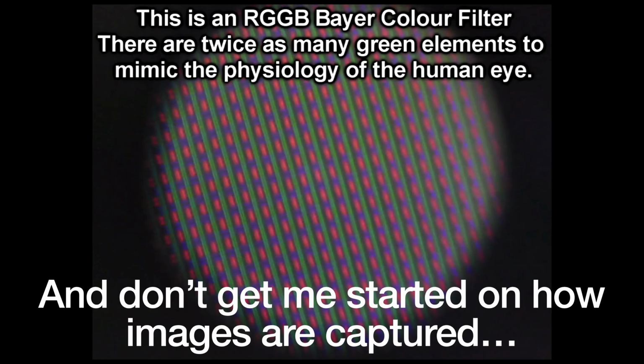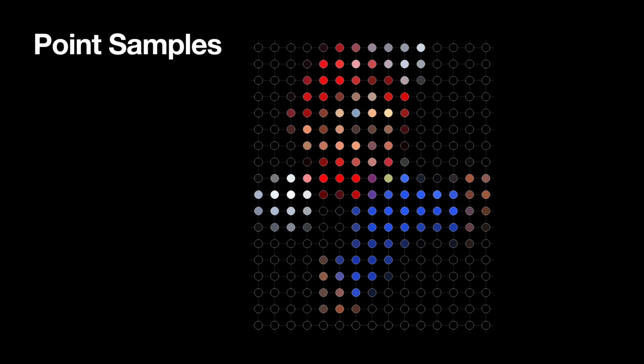And don't get me started on how images are captured. Even if we have a sensor that is a square shape, we'll be taking the average value over that square and probably applying all sorts of processing before we get the actual data. So what is a pixel? Well, our grid of pixels is actually a grid of point samples. Each pixel is a measurement taken at a particular position. It's the colour or brightness at that point, and the point is infinitely small.